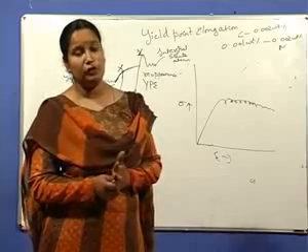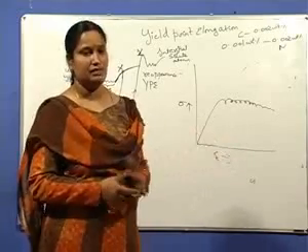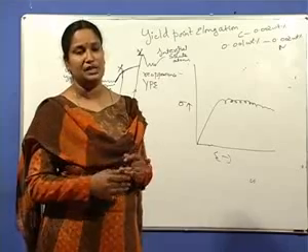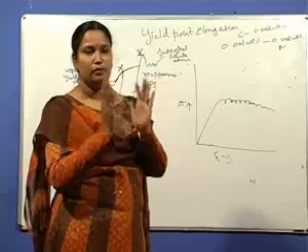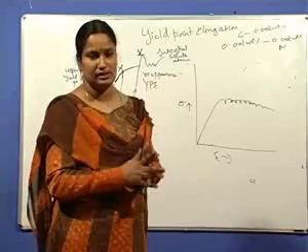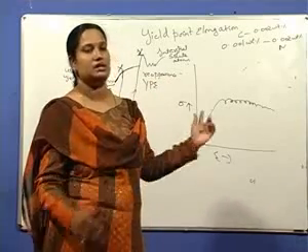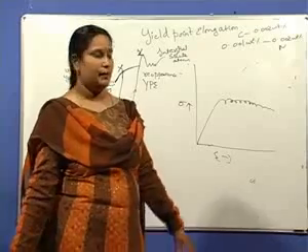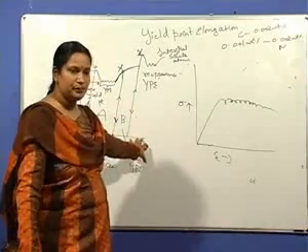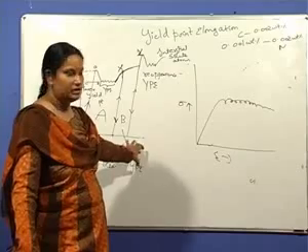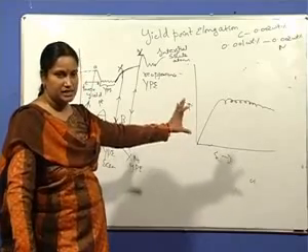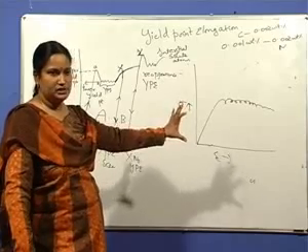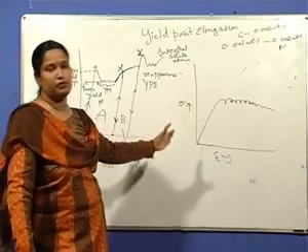But again, beyond 400 degrees, you don't find this. Why? Because at such higher temperatures, the formation of these Cottrell atmospheres does not occur, so this effect is not seen. This is static strain aging, that is the room temperature aging, whereas if the strain aging occurs at slightly higher temperatures and during deformation, it is dynamic strain aging.